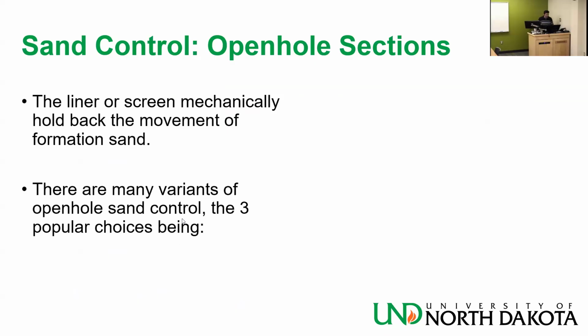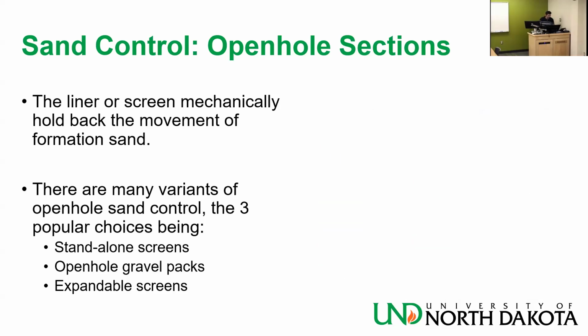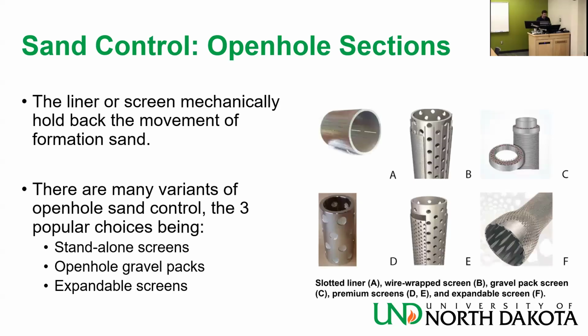There are many variants of open hole sand control. The three most popular choices being standalone screens, open hole gravel packs, and expandable screens. Here is an example. With A, we have a wire-wrapped screen. I wish there was one with slots to be transferred rather than vertical.